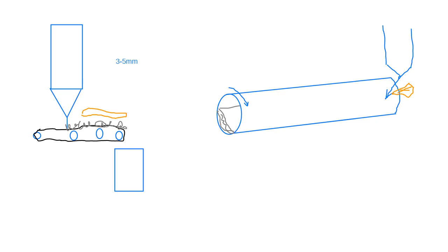Let me just see if I can catch these things. Oops. I'm going to just pull this flame and put it in this way. So the flame gas is coming in pointing in that direction. I'll give some more pencil marks to make the flame point in that direction. Okay. So the flame is coming in there, hot gas, counter current to the material movement, and then your gas saturated with water will be coming out on this side, or almost saturated with water.